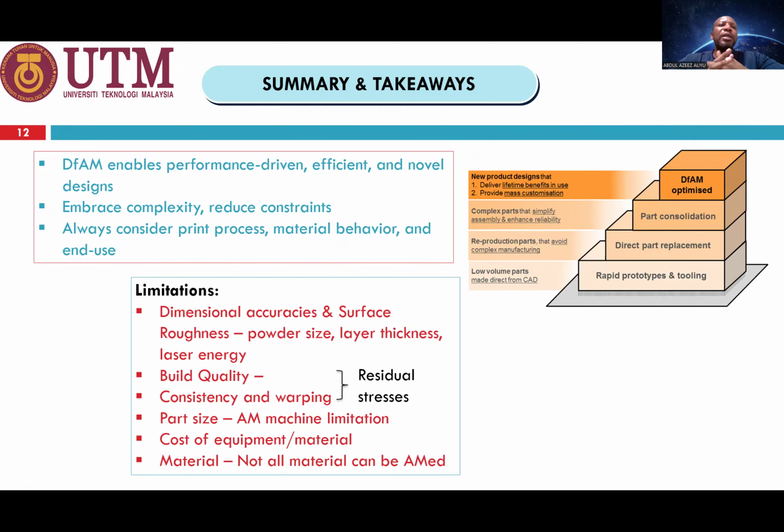And also the quality and consistency, and warping resulting from additively manufactured parts, which results in residual stresses. So research is ongoing, like employing heat treatment or annealing processes that can overcome this generation of residual stresses.